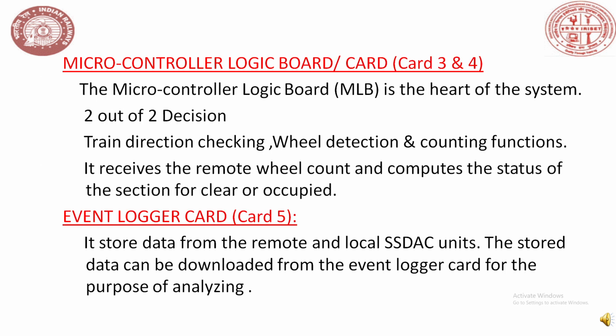Microcontroller logic board or cards, that is card number 3 and 4. The microcontroller logic board, MLB, is the heart of the system: 2 out of 2 decision, train detection, checking, wheel detection, and counting functions. It receives the remote wheel count and computes the status of the section for clear or occupied.